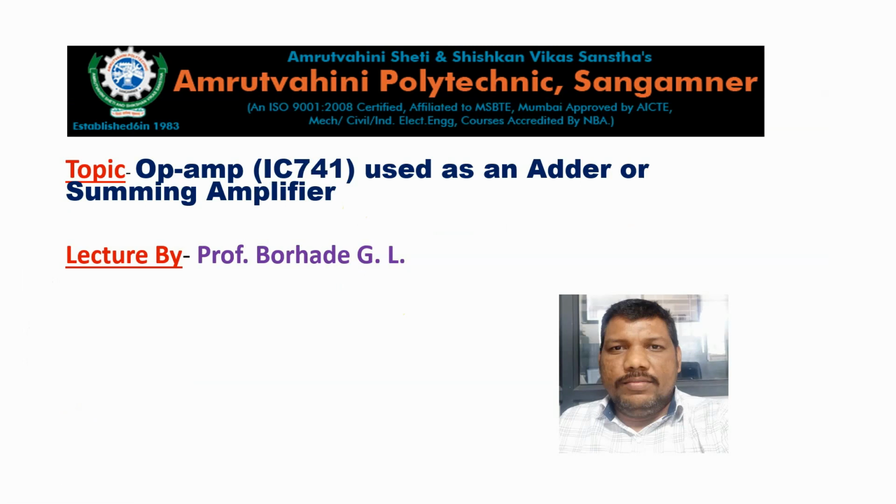Myself Borhade Ganesh. Today we will learn how an op-amp can be used as an adder or summing amplifier. The operational amplifier, that is the IC741, can be used as an adder or summing amplifier. Adder means if more than one input signal is applied to the inverting or non-inverting terminal of the op-amp, then the output is the addition of the input signals. Therefore, this circuit is called an adder or summing amplifier.